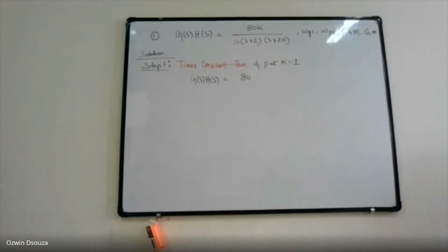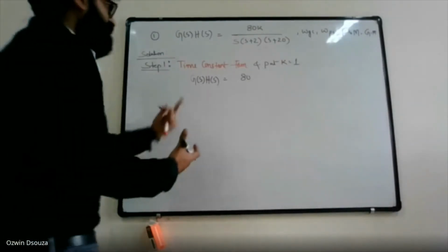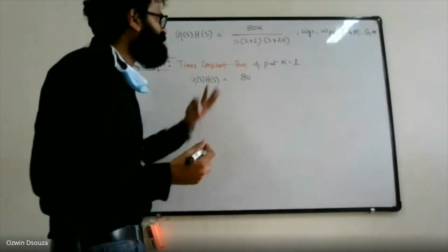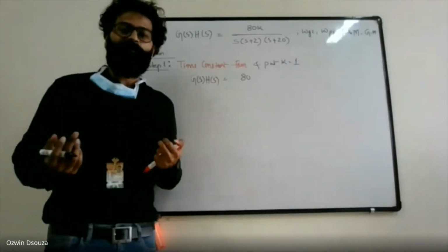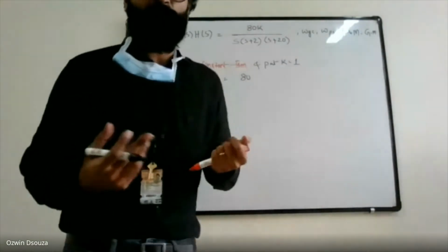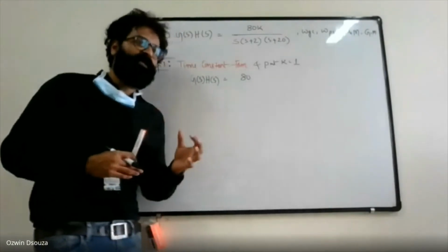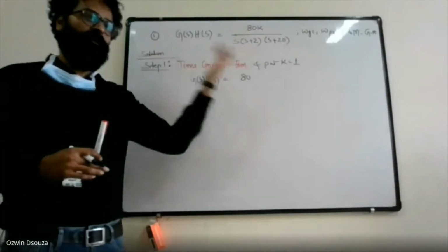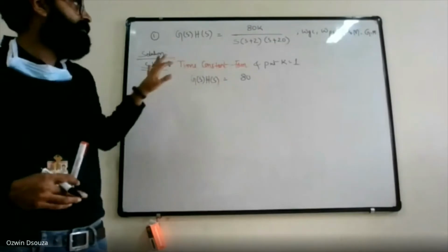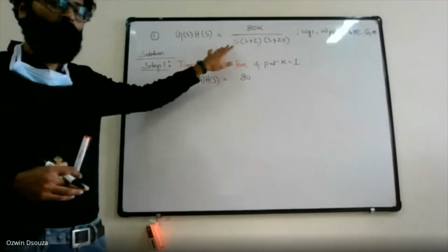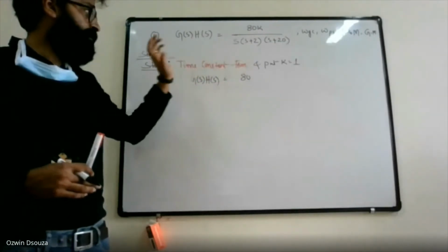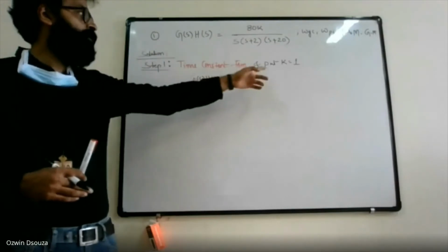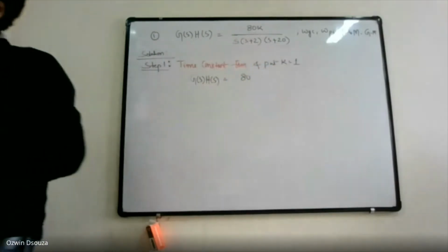And the remaining information can be extracted from the Bode plot. Sometimes they will say take k is equal to 10 or say k is equal to 15. So if they specifically mention, you can take the value. If they haven't mentioned, for example, in this problem, they haven't mentioned the value of k, then to start drawing Bode, you can put the value of k as 1.